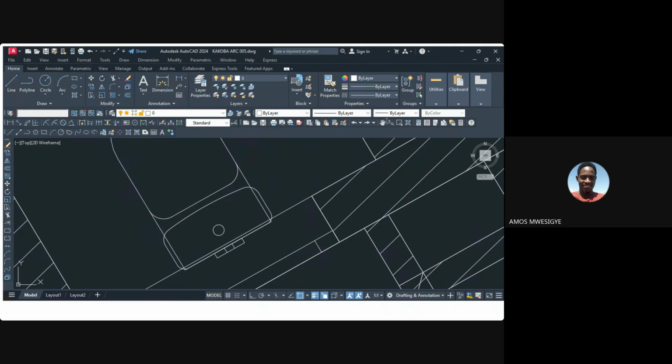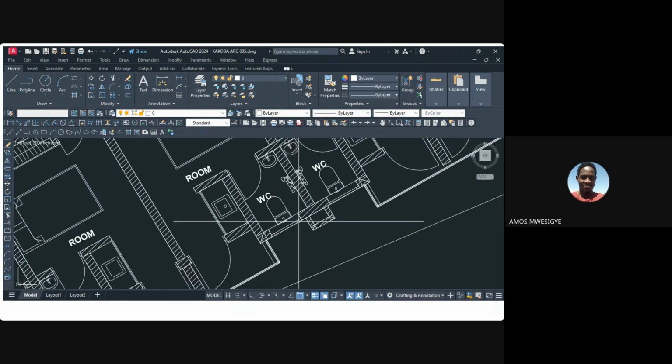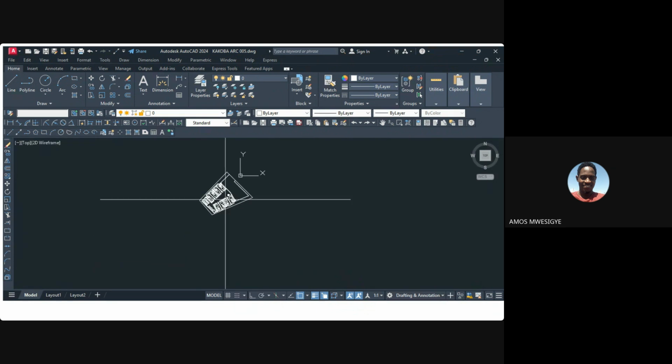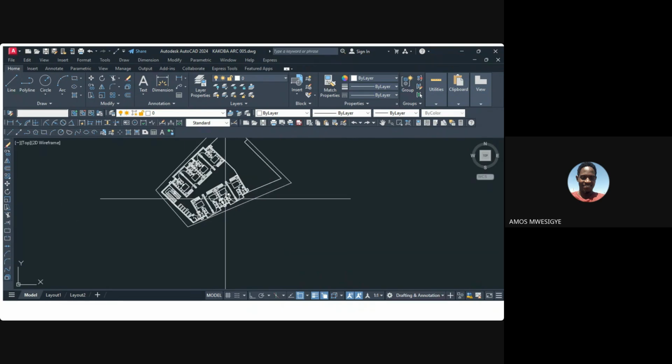So you want the wall to come back to 200 millimeters thick. You divide by what you have. So when I enter, I'm getting a scaling factor of 0.1097. For the other PDF, we got a scaling factor of about 2,000 because the drawing was really very small,